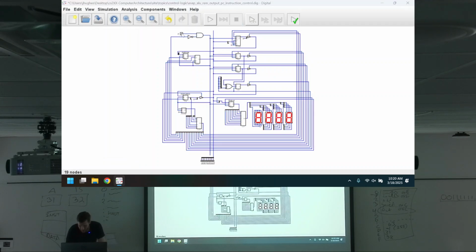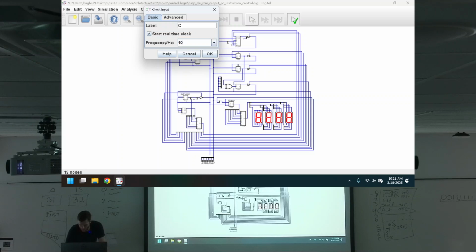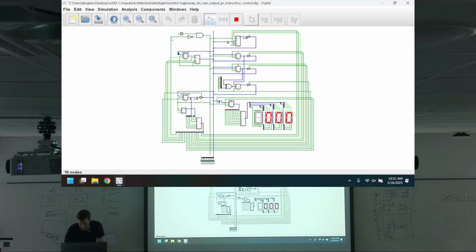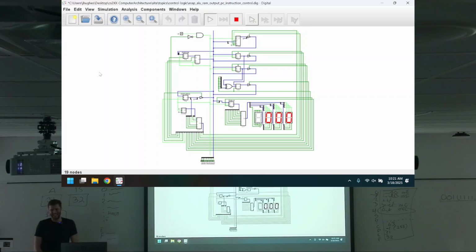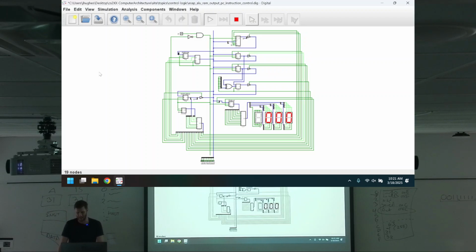Now, for the sake of one more little bit of fun, let's put it on a 1 hertz clock. You will see that it actually takes a few seconds here, right? Like, look, it's running these instructions. Each clock cycle, you know, we're getting 1 a second, so this could take several seconds. Each instruction takes 4 seconds effectively. And how many instructions did I have? Like about a dozen or something, right? Well, finally we get 63.